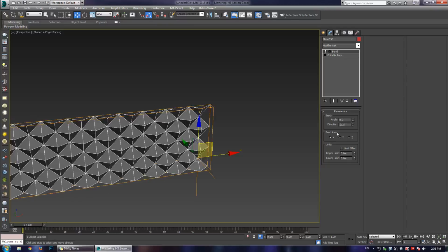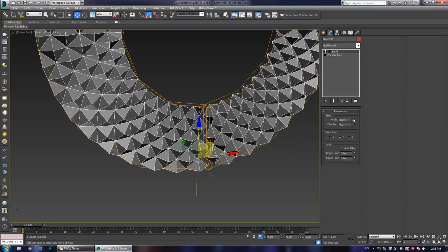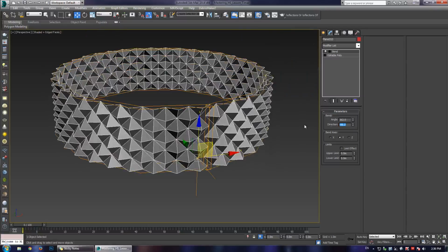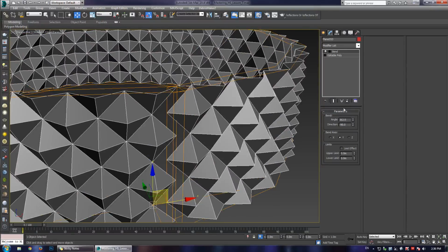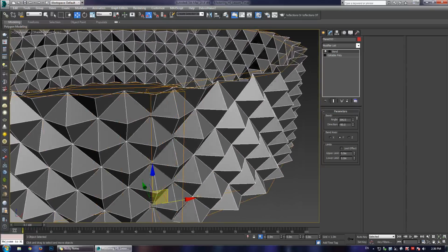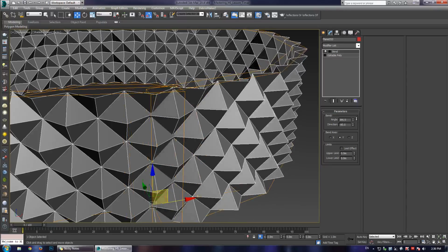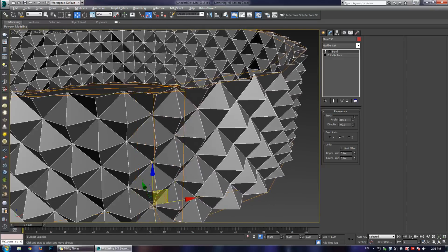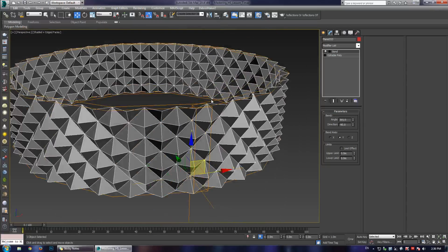Sometimes you just need to experiment with that. I think I said in a previous lesson it's always pretty unlucky with whether or not it works. So in this case, I'm going to go to -90 on the angle. And then using Alt, which when you drag over a slider box and you don't have anything selected, you'll notice that it goes up at a higher value sometimes than you need for accuracy's sake. So in this particular case, 365 is the exact angle that it needs to snap. And you can see we're moving up in 0.5 increments. But if I hold Alt now, you can see that it can go up by 0.05. So I'm just going to leave it at 365 and collapse this object.